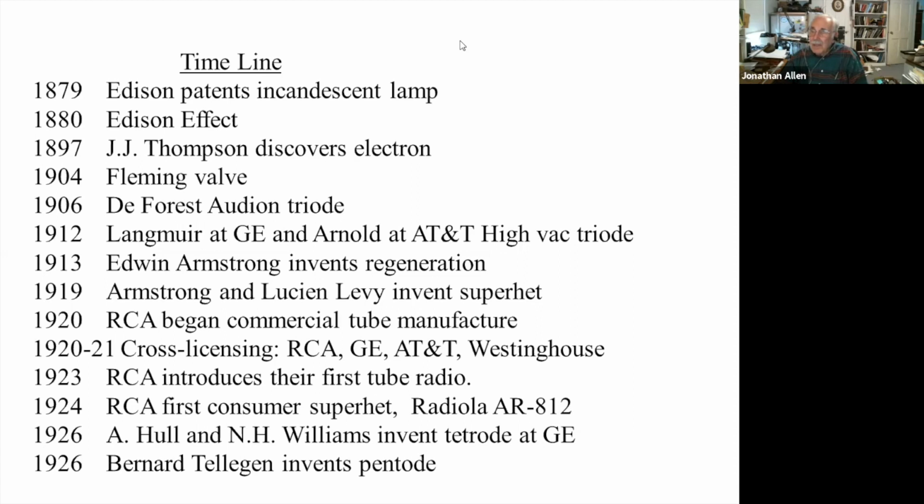The only tubes that in modern times use the directly heated cathode, or the filament as the emitter itself, are battery tubes used in portable equipment, where you want to absolutely minimize the drain on the A battery, and also in high power transmitting tubes where you need to get really a lot of emission, and you want to enjoy that really high temperature of the filament itself. And there, the 5 volts or something across the filament is not going to make any big difference to the RF, because you're dealing with thousands of volts on the plate.